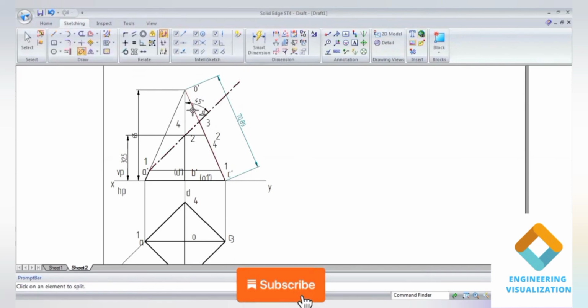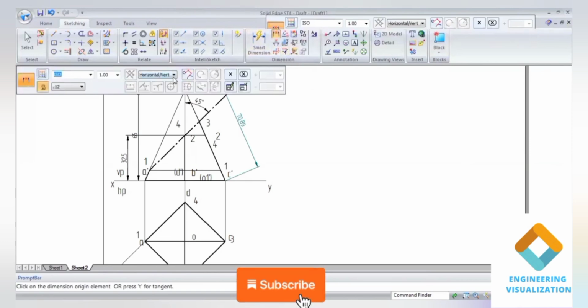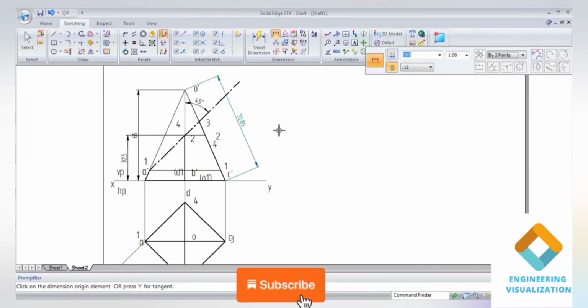So for this I'll be using the split command to get the exact length here. In the distance between command there is an option here. So distance between 2 points, if you select, you can measure the dimension. This is an important step, guys. You can make use of this particular command. So select these 2 points, this will give the slanted line.